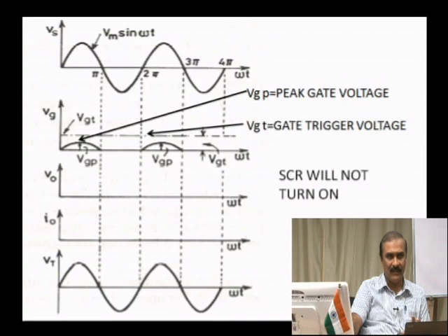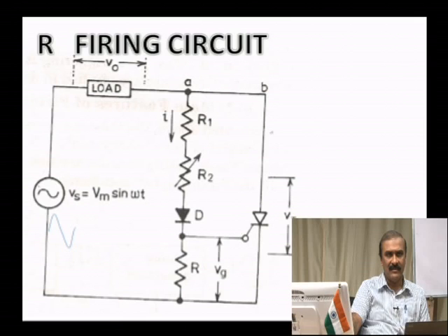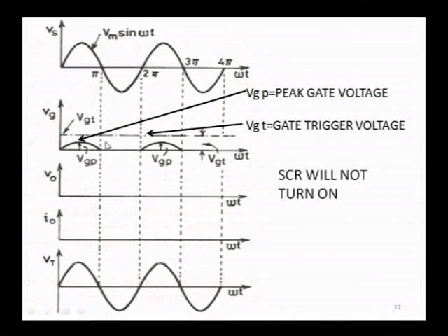If you refer to the diagram, you can see the diode connected in series with the circuit. So, this diode allows only positive half cycles. That is why only half cycles are shown here, negative cycles are suppressed. Now, the other line, the dotted line, is VGT, the gate trigger voltage. In the next line you can see V naught, no waveform is shown here, it is 0.